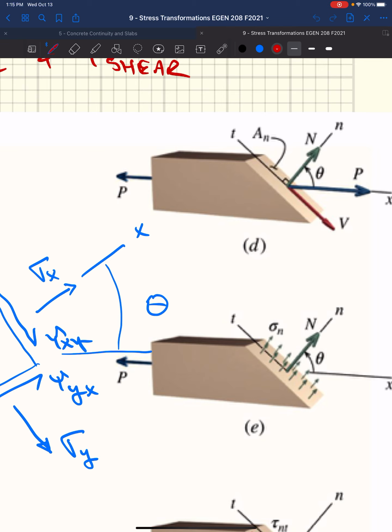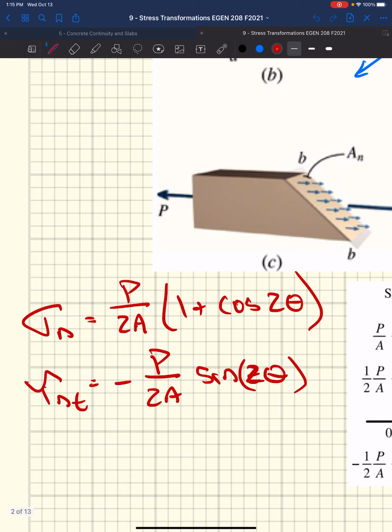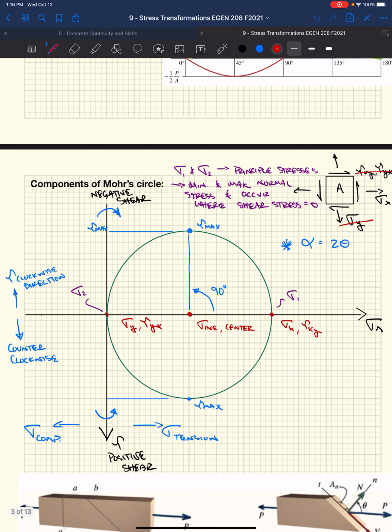So if you did that, you essentially develop these 2 equations that give us what that stress is. Well, Mohr's circle essentially puts those into a larger depiction that allows us to incorporate both torsional stresses, axial stresses, bending stresses all together into one, okay?